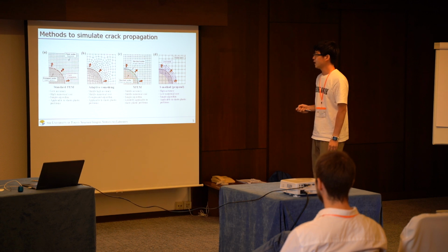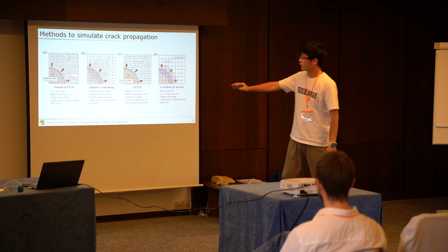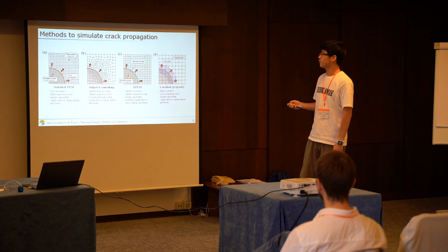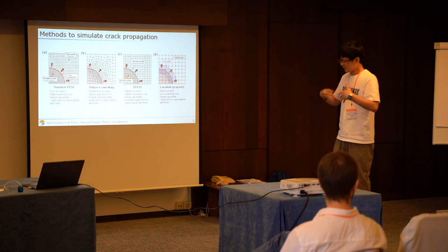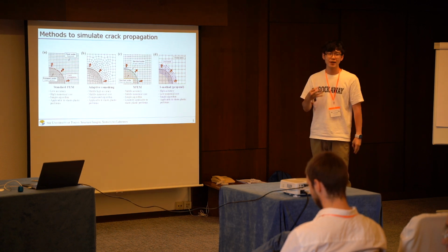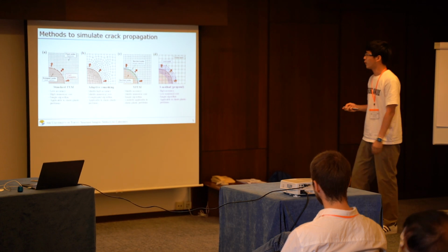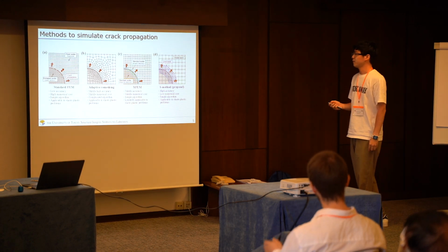In the XFEM, enrichment functions are used to simulate the crack front. You can see the mesh is also very simple, but it is of limited applicability to elastoplastic problems because of the enrichment functions. Finally, there is our proposed method, based on the expression of finite element method.